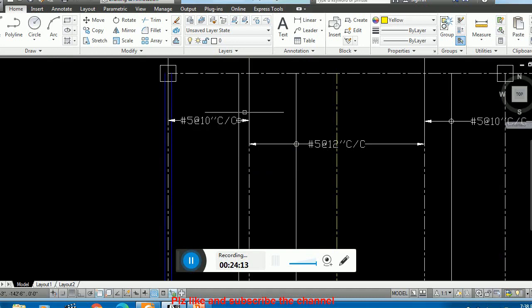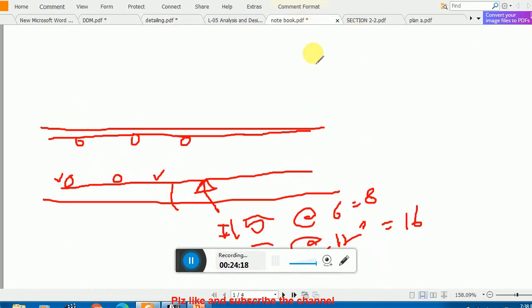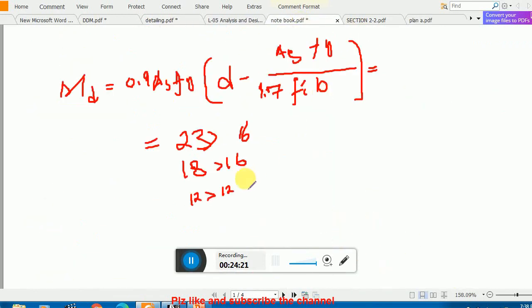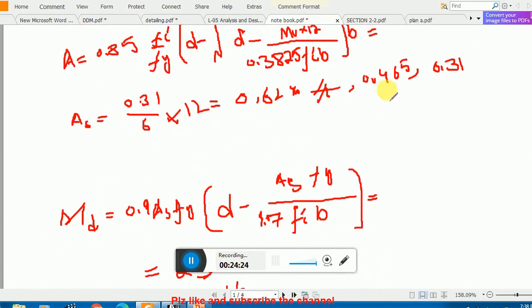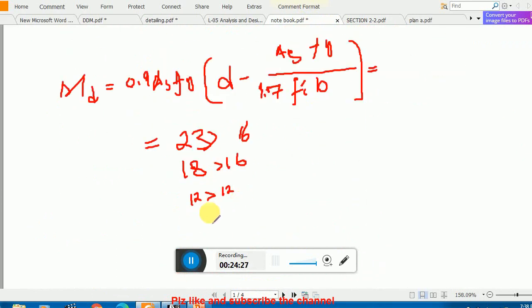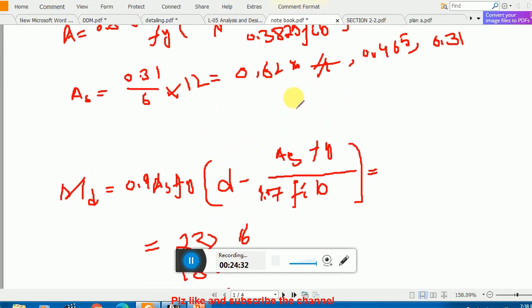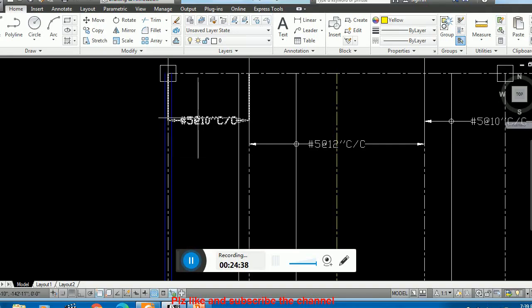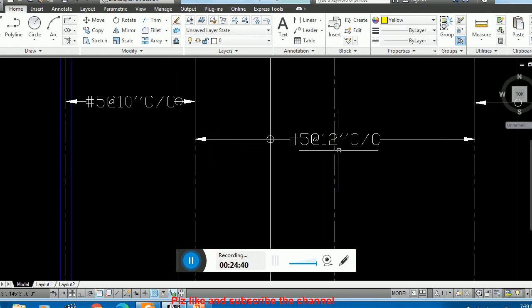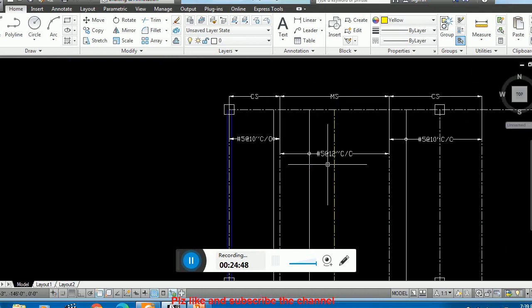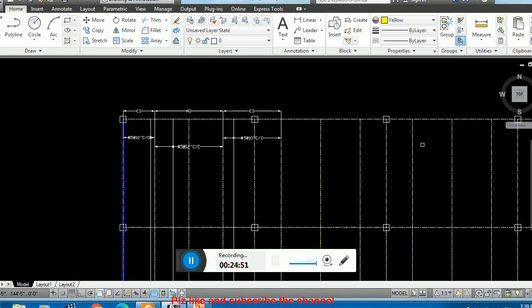Although this amount of reinforcement is the maximum, you will be allowed to use, let me show you. Here you see, if you use, let's say, 12 inch center to center, you see the amount will be on the same side. So that's why I'm using, although I'm using 10 inch, you can use 11 inch as well as 12 inch instead of this 10. And similarly for 9 you can use 13, 14, 15 inches as well. But I'm using this amount of reinforcement through all panels.